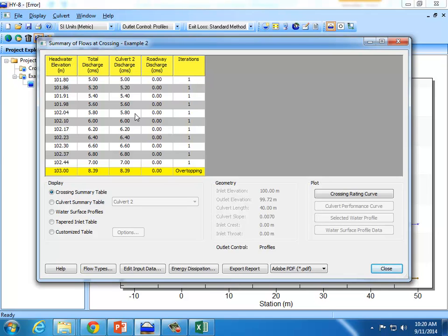Yeah, the difference isn't jumping out at me. The only thing is, you had a 4 here, I have a 5. Like a top width? Yeah, but I didn't think the roadway stuff mattered. Yeah, since we're, let's see, analyze possible. I'd have to look at it more closely. I don't know. When in doubt, just start from scratch. Okay. So, yeah, delete the culvert and put in the crossing again.